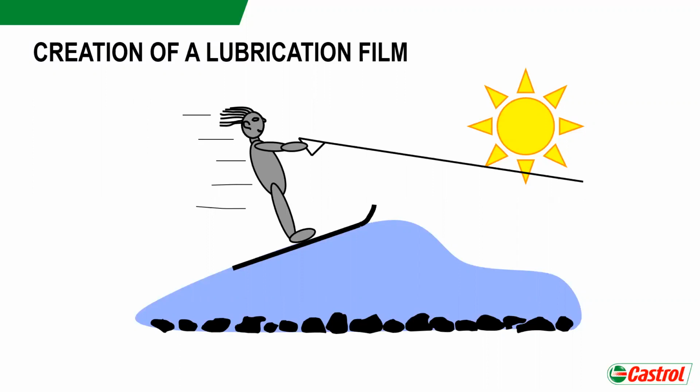But replacing the lake water with honey, it will be different. Then, because of the higher viscosity of the honey, the lubrication film will build up faster at lower speeds. This is also a hint for our machines and lubricants in the machines. If we have low speed applications, which are maybe also highly loaded, then we need a high viscous fluid to build up the lubrication film right and fast.